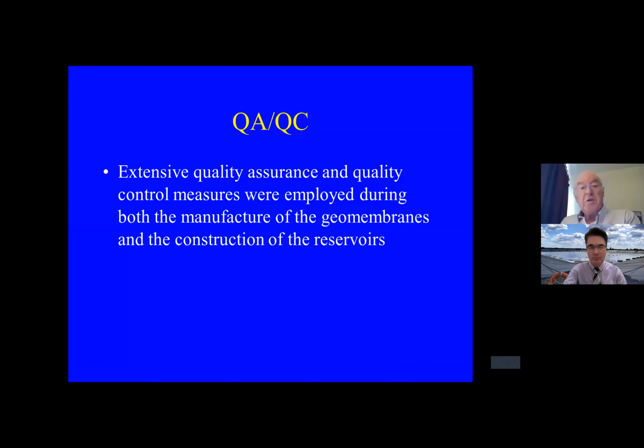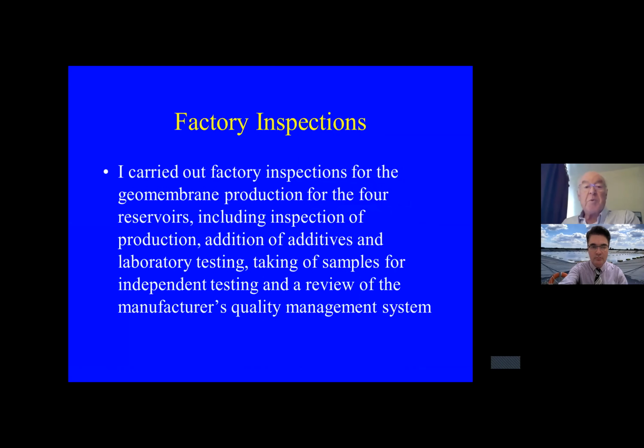Right, moving on to QA/QC. There was extensive quality assurance and quality control measures during both the manufacture of the geomembranes and the construction of the reservoirs. Starting with factory inspections, I carried out the factory inspections for the geomembrane production because the geomembranes were produced here in Asia for the 4 reservoirs, including inspection of production, addition of additives, and laboratory testing of the membranes, taking samples for independent testing, and I carried out a review of the manufacturer's quality management system.